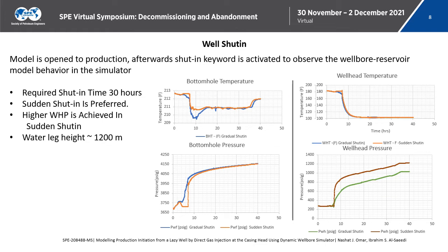It's very necessary to evaluate the transient behavior of a well whenever it's shut in. This provides very valuable information. For example, we can determine where the gas-liquid contact is placed inside the well. Additionally, it shows us the pressure and temperature distribution inside a well or at any given point of interest.